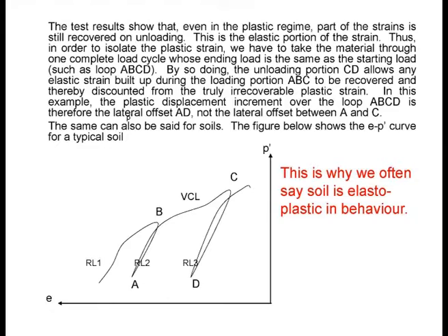Just now I told you that the simplest way of showing people that soil is elastoplastic is to just use your footprint. But there are other ways of doing it. You will still remember in your one-dimensional consolidation, you plot the e-log-p curve. You know that? And you got the recompression line, and then the virgin compression line, and then the swelling line, and then the recompression line, and so on. Let us take this opportunity to revise a little bit on that.